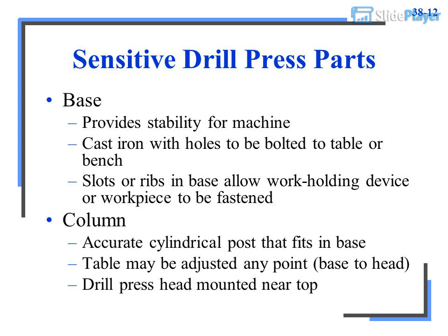Drilling head. The head, mounted close to the top of the column, contains the mechanism used to revolve the cutting tool and advance it into the workpiece. The spindle, which is a round shaft that holds and drives the cutting tool, is housed in the spindle sleeve, or quill. The spindle sleeve does not revolve but slides up and down inside the head to provide a down feed for the cutting tool. The end of the spindle may have a tapered hole to hold taper shank tools or may be threaded or tapered for attaching a drill chuck, figure 38-2.